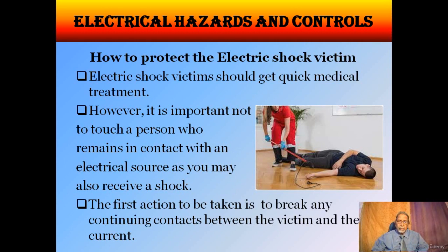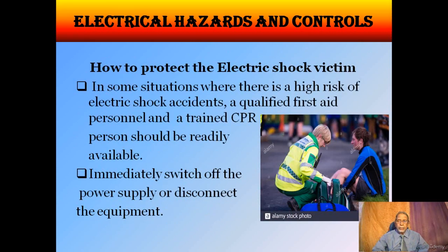The first action to be taken is to break any continuing contact between the victim and the current. In some situations where there is a high risk of electric shock accidents, you need qualified first aid personnel and a trained CPR person who should be ready and available for the treatment. What should you do? Immediately switch off the power supply or disconnect the equipment.